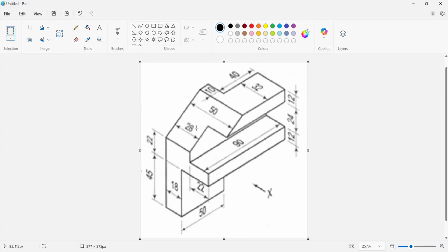On the similar line, as you can see, this triangular, this taper edge which is available. Right now I have a rectangular edge, so I will cut a triangular shape from it to get this taper shape. So for that, the height of the triangle will be total height 93 minus 45 minus 22. So instead of calculating, we'll try to see how we can draw actually with help of